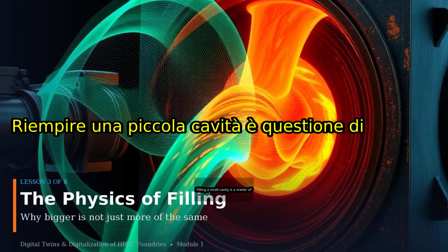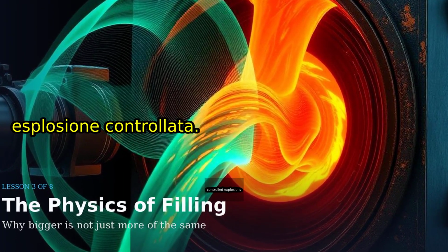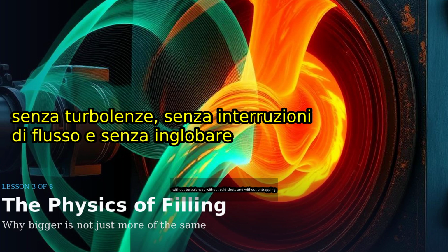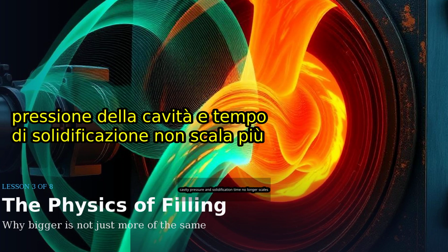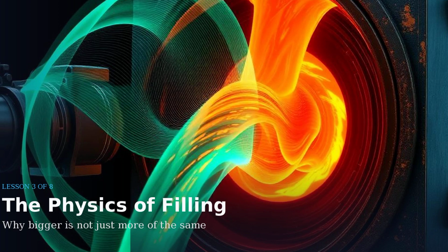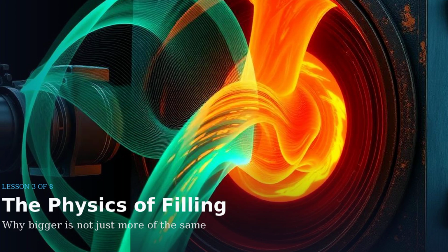Filling a small cavity is a matter of milliseconds. Filling a 2-meter structural casting is a controlled explosion. Molten aluminum must travel meters through complex runner systems at velocities exceeding 40 meters per second, without turbulence, without cold shuts, and without entrapping air. The relationship between gate velocity, cavity pressure, and solidification time no longer scales linearly. Small errors in shot profile that were invisible on a bracket become catastrophic on a rear underbody. This is why intuition and legacy process sheets are no longer sufficient.